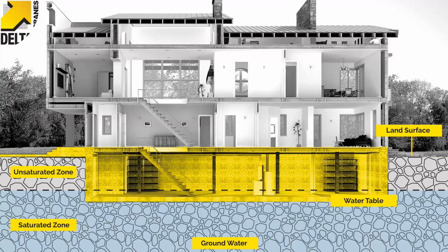So generally speaking, just assume that the water table will reach to the full height of the basement at some point during its lifetime, because it's variable, it can change. We're not weather gods. We can't predict what's going to happen underground, how much water there'll be, climate change, flooding, all sorts of things, yeah? So we just assume that the water table is going to be to the full height of the basement.